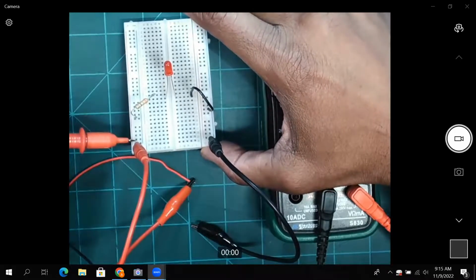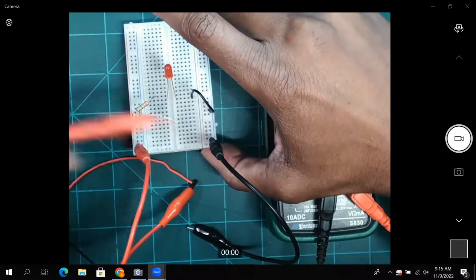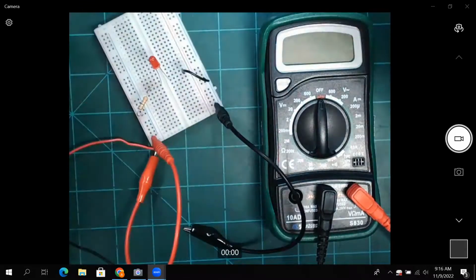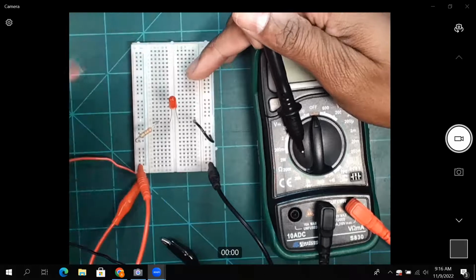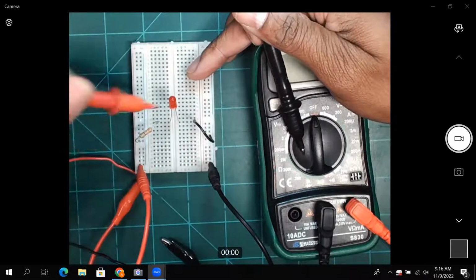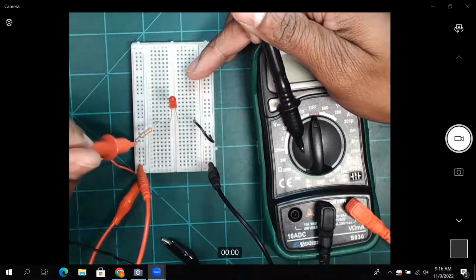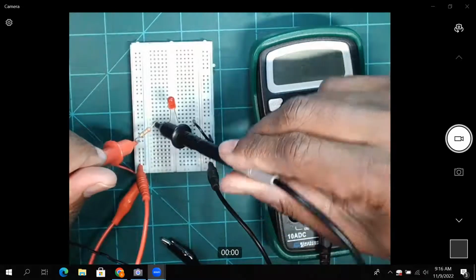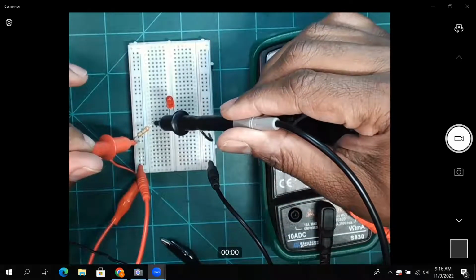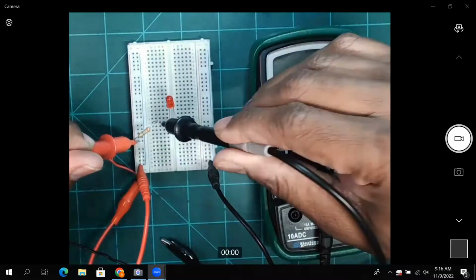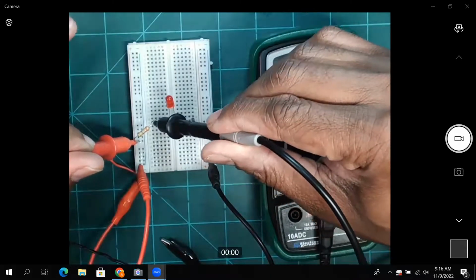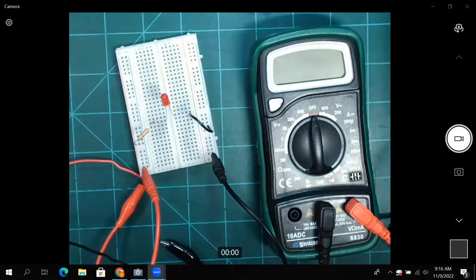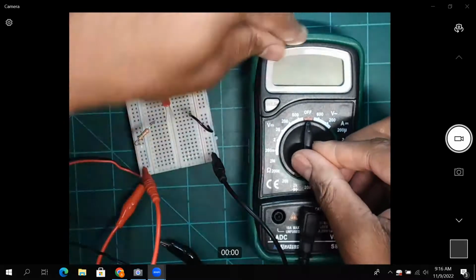So you're going to check your voltage at the battery source in parallel, meaning that given that this is a series circuit, there's only one path for current to travel. Well, when you measure, let's say, the voltage at the resistor, now there are 2 paths for current to flow: through the series circuit and through my multimeter. Therefore, I am measuring this component in parallel. Okay, so let me just give you a quick example.